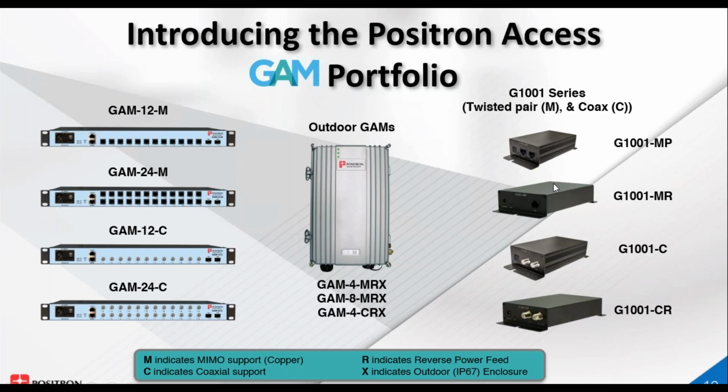So this device is slightly larger because of the G1001 MPOC, because it has the circuitry to inject 48 volts on the pair or the coax port and the coax one towards the GAM. We picked 48 volts because if your techs happen to touch the pairs where there is power, there's no concern, you really feel just a bit of a tingle. So no concerns about their health, their well-being, but it's easy also to operate inside over the existing wiring without causing any overheating issues or range issues.